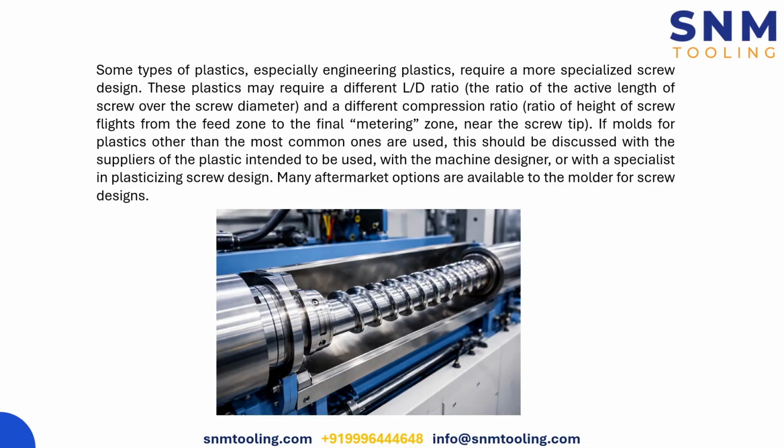For polyolefins like polypropylene or high density polyethylene, we generally prefer the use of general purpose screws. So, what is the crux when it comes to selecting a screw for a specific material? If we design a screw for PP, that does not necessarily mean it will perform equally well for nylon or PET. Rather, it can perform poorly for nylon or PET.